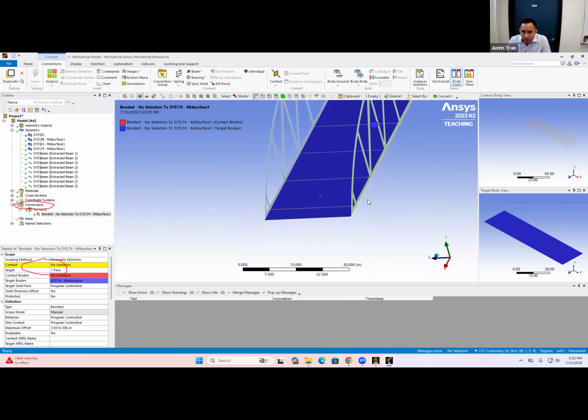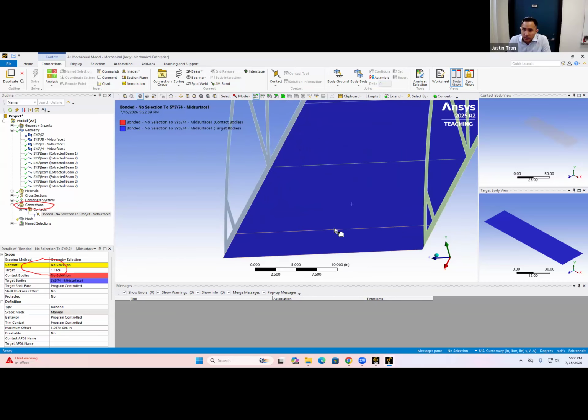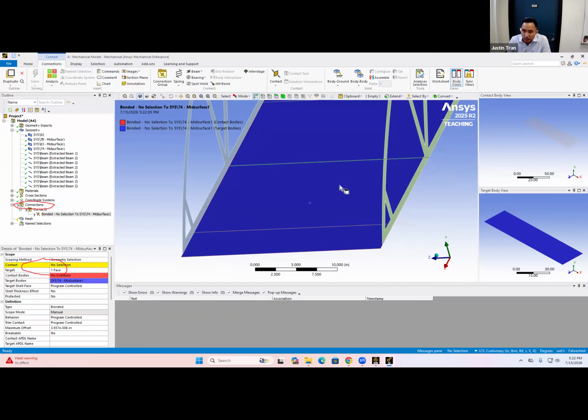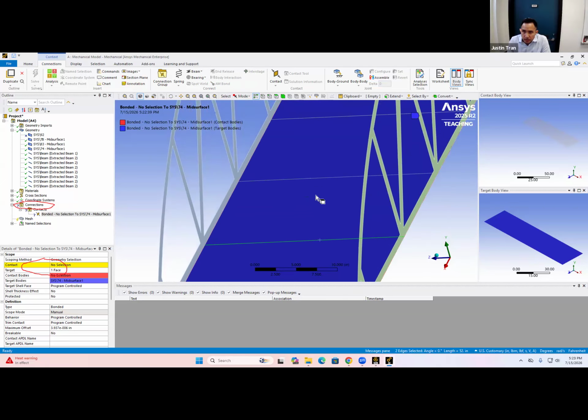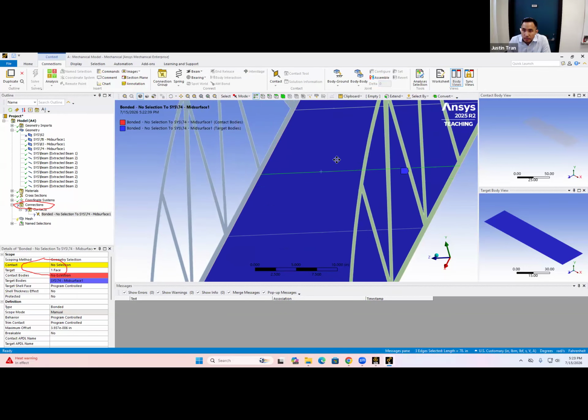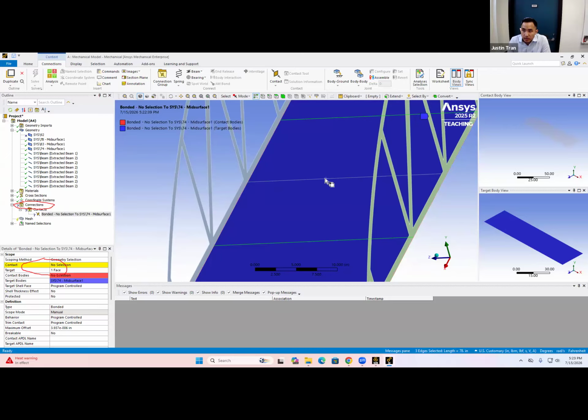It's going to be a little bit of a delicate process because you have to mouse over the beams exactly, so zoom in and pan if you have to. You're going to left click on each of the beams here, holding Control on your keyboard to make sure that you're selecting all of them. Select that one.